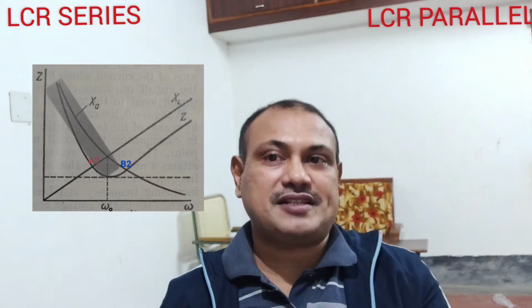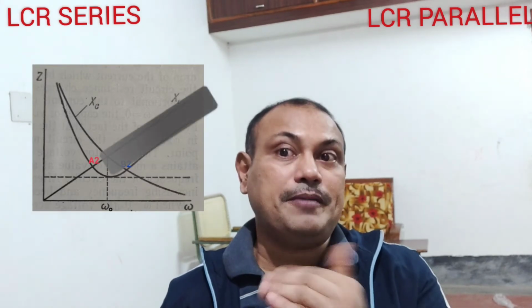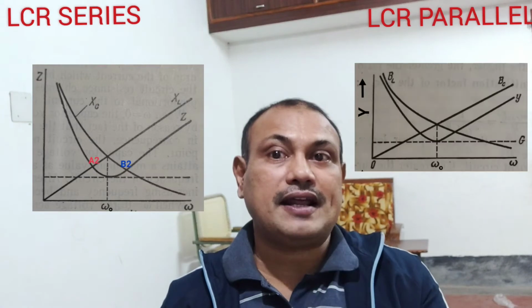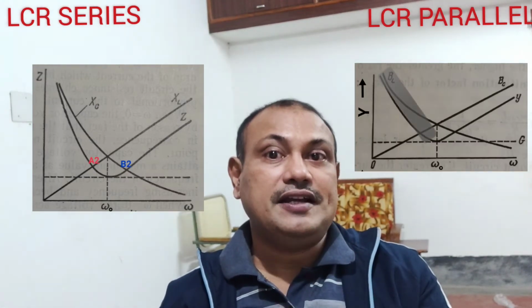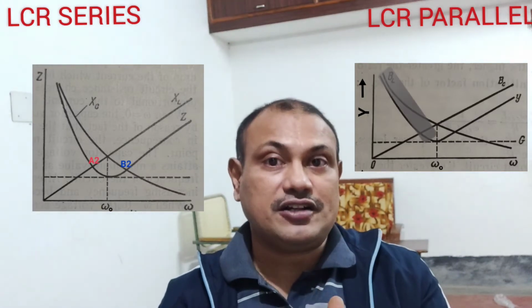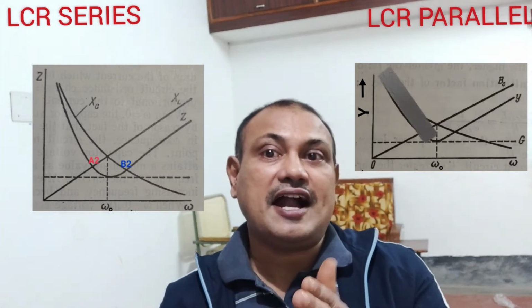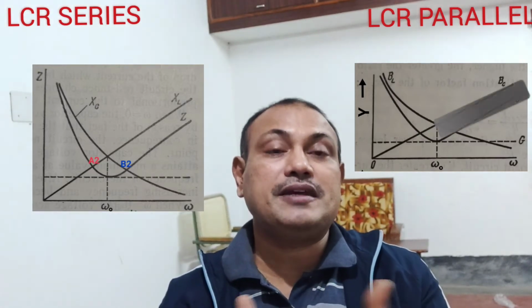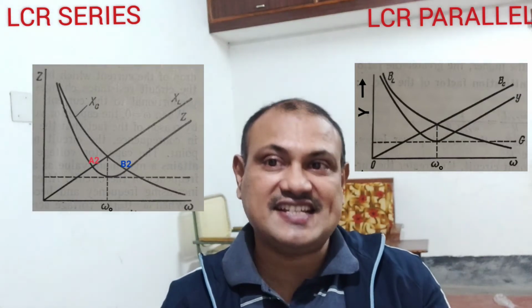Looking at the diagrams, below the resonant frequency, the LCR series circuit effectively behaves as capacitive, and above the resonant frequency, it behaves as an inductive circuit. But in LCR parallel, below the resonant frequency, the circuit behaves as inductive, which is the reverse of LCR series, and above the resonant frequency, it behaves as a capacitive circuit, which is again opposite to LCR series.